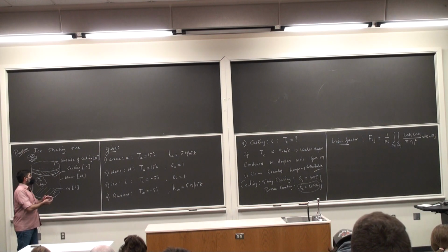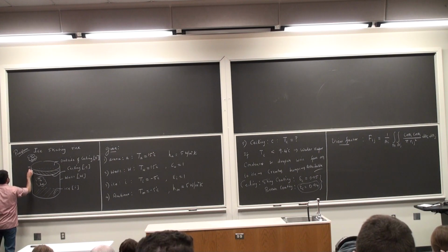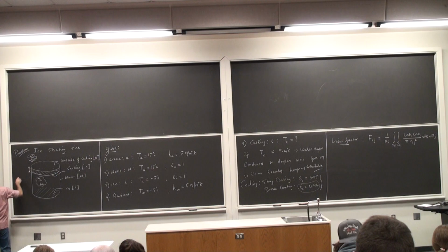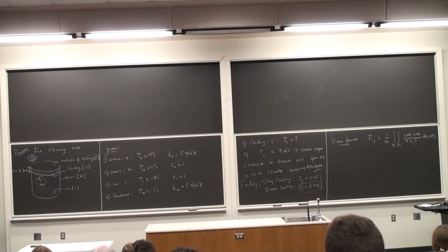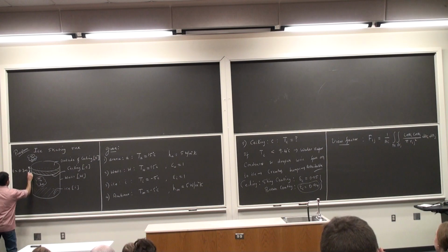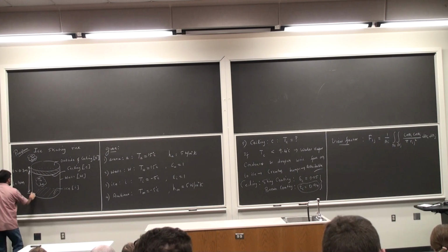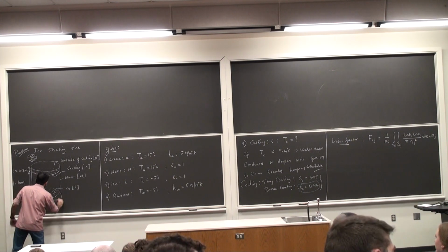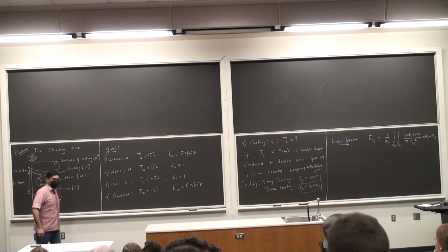So if I'm considering the interaction between 2 cylinders, the dimensions need to be given. This is the thickness, 0.3 meters is the thickness of the ceiling. The total height from the ice onto the ceiling is 10 meters. And then the diameter, 50 meters. It's a mid-size hockey rink.